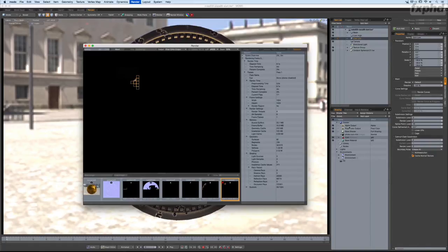It's still going to follow the coloring book, if you will, that we created with the UV map for our low resolution object, and now it's going to take all of the information that this render output is creating and place it inside of an image map, and you can already get a good understanding of how long it's taking the computer to evaluate the high quality, final quality image of all those occlusion rays that we created inside of my material network. So it's taking a little bit of time, but the cool thing about this is that we're only doing it once, right? We're only committing to one single long render as opposed to many long renders, which I, for one, am really quite thankful for.